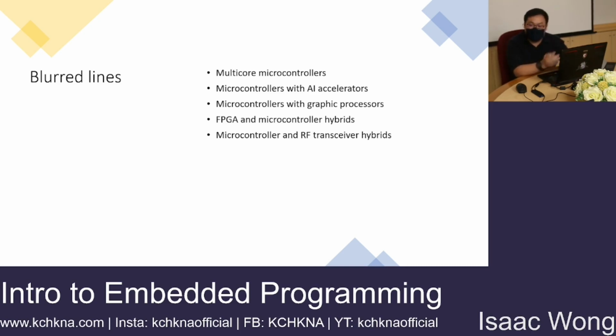And then microcontrollers with AI accelerators on board. What this means is that you don't even need the microprocessor anymore. You just run everything in the AI accelerator. Then you have microcontrollers with graphic processors, so you can run graphic applications that can power an entire screen just from a microcontroller, which wasn't possible maybe 10 years ago. You have an FPGA microcontroller hybrid, and you have a microcontroller and RF transceiver hybrid. So people are starting to put together things that weren't available before, and such integrations of different things inside enable you to make very high performance and really compact designs.